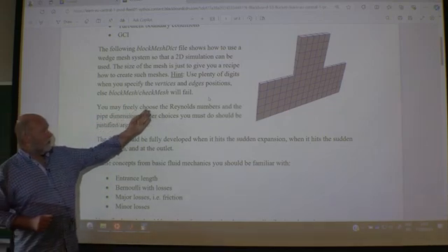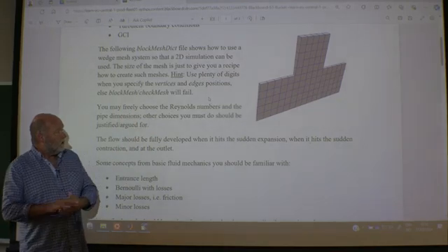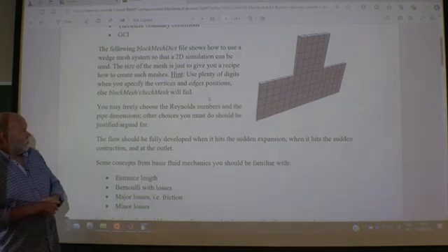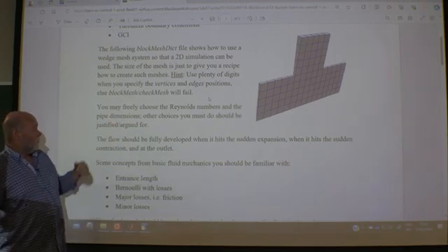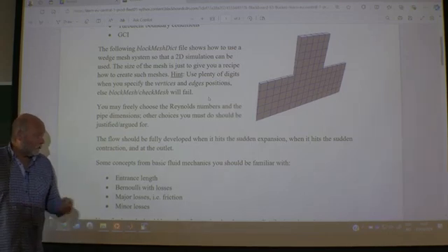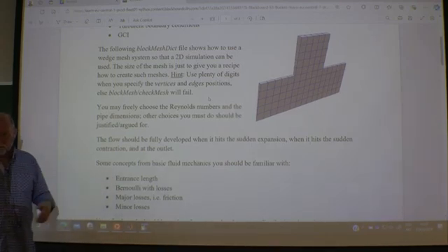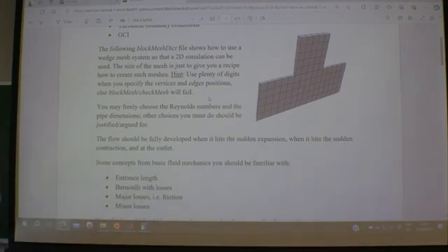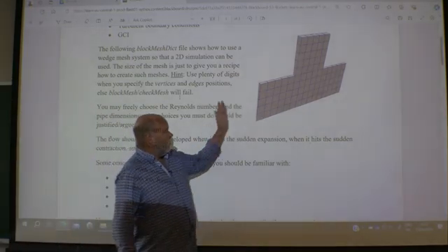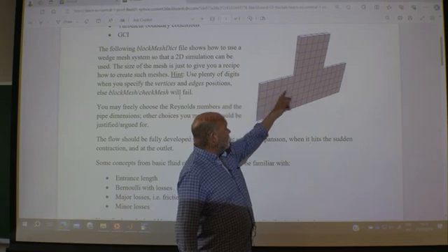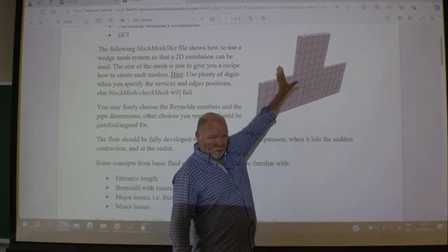Here you don't really need any arguments. Well, it may be a question about the pipe lengths, because there is something you need to address here called the entrance length. That's something you have to look at, because the flow should be fully developed when you start at the inlet and then hit the sudden expansion.